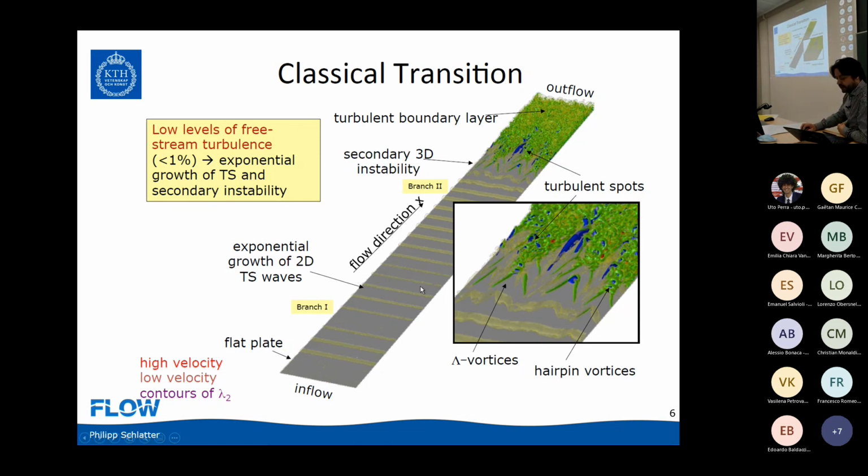And now these yellow lines or sausages that are oriented in a spanwise direction, these are the TS waves. And as we were discussing, they're two-dimensional. They're two-dimensional because we know it's the two-dimensional waves that actually become unstable first. Right?